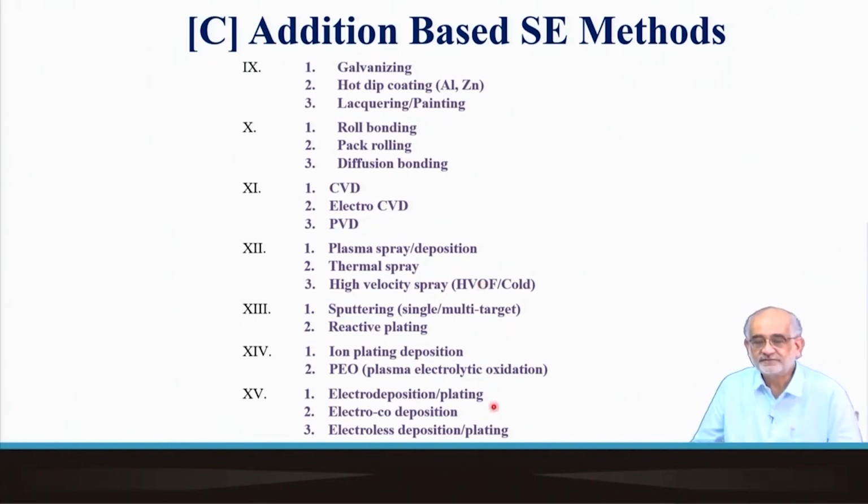You can do sputtering, which basically is shooting specific atoms onto the substrate. You first use something to remove atoms from a target. So you use a very high energy argon ion, which actually goes and hits the surface and scoops out some atoms from a target, and that target material now, as a neutral, moves over an evacuated space, and gets deposited on a substrate which is kept somewhere around.